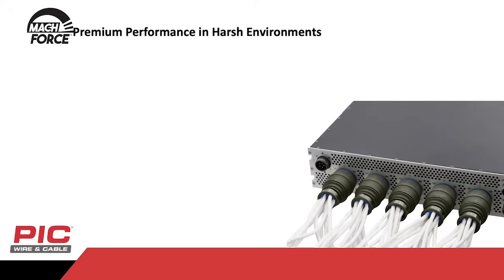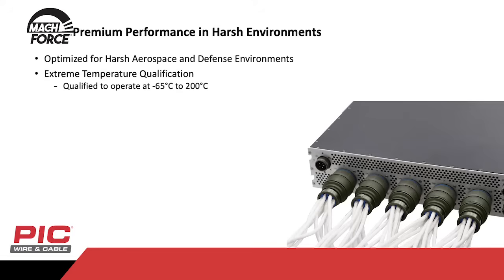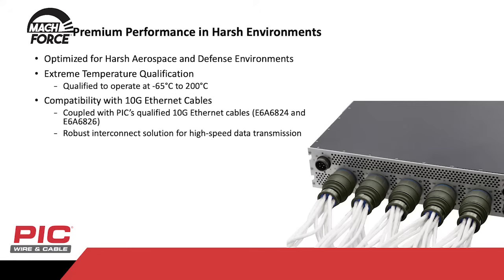Next, I'd like to talk about robustness. The MACHFORCE connector was optimized to provide premium performance in harsh aerospace and defense environments. These connectors have been qualified to the extreme temperatures of -65 and 200 degrees Celsius, and when coupled with PIC Wire and Cable's 10G Ethernet cables E6A 6824 and E6A 6826, which have also been qualified to 200 degrees Celsius, you have an extremely robust high-speed data interconnect solution that is capable of performing in harsh military and aerospace environments.